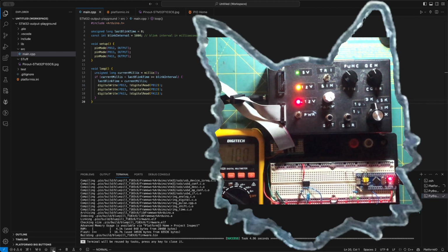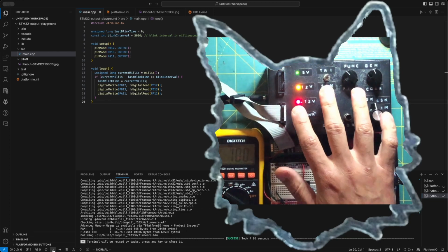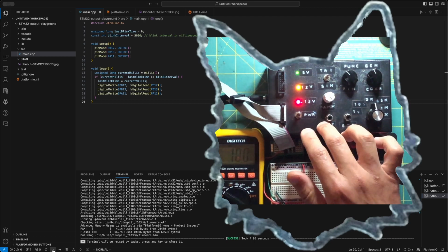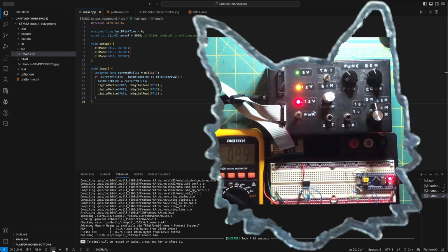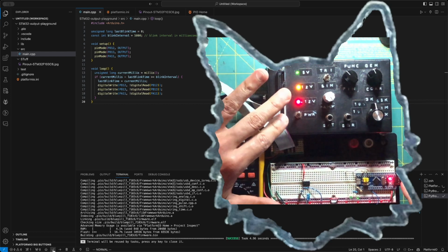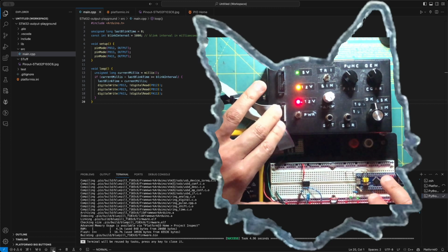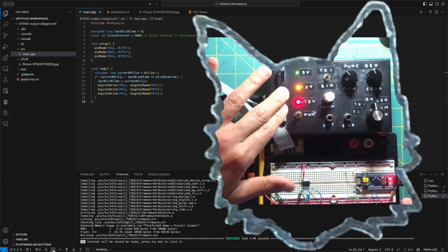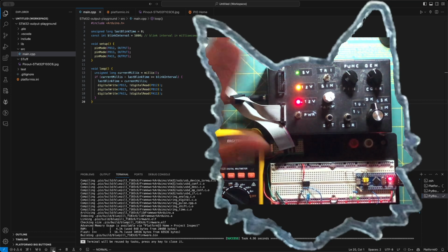One thing to note, because I am powering this from an external power source, on my ST-Link I only have ground and the 2 signal pins connected. I left the 3.3 volts unplugged. Okay, we definitely don't want to send power from an external source and power from the USB at the same time, as that could damage the microcontroller.